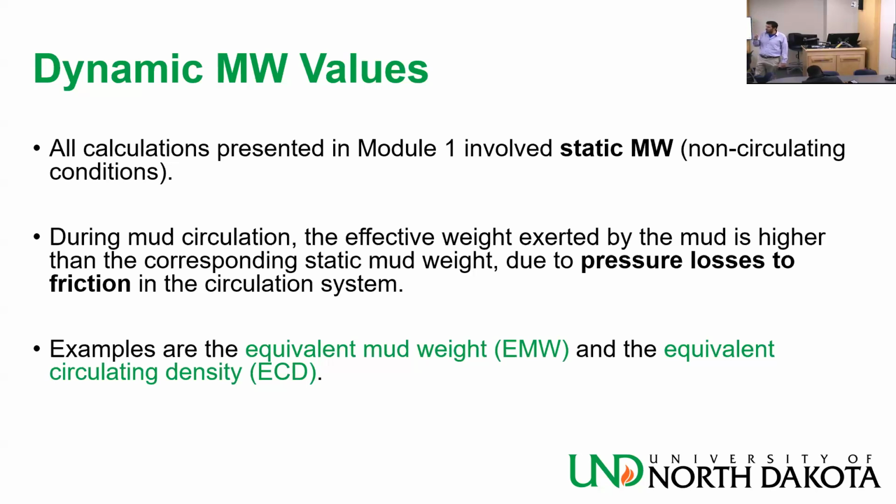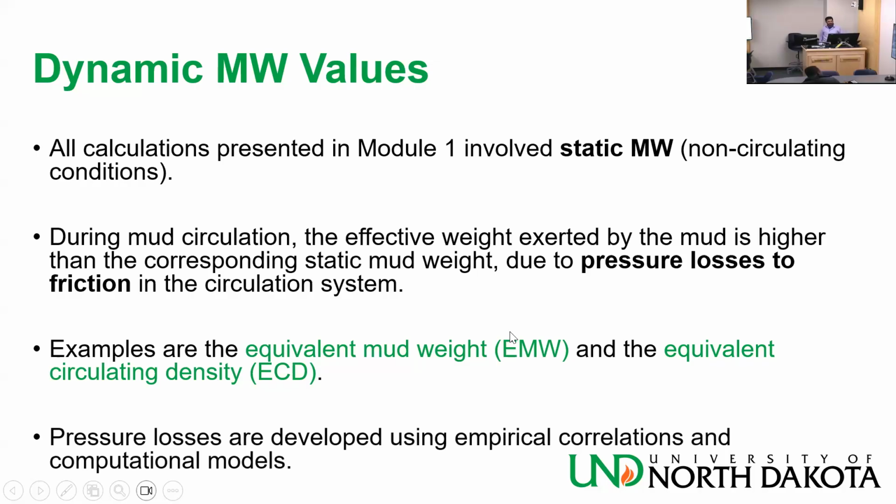ECD is an equivalent mud weight value at specific conditions. So they are the same thing. ECD is an EMW value at a certain location, at a certain depth. ECD is an EMW value, but EMW is not ECD. EMW can be a lot of stuff other than ECD. And we're going to see that when we learn how to do the hydraulic loop, which is very important.